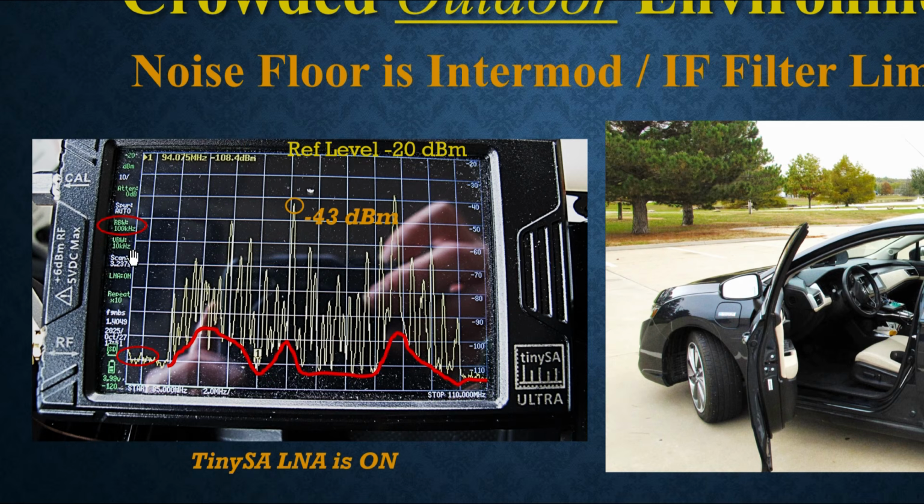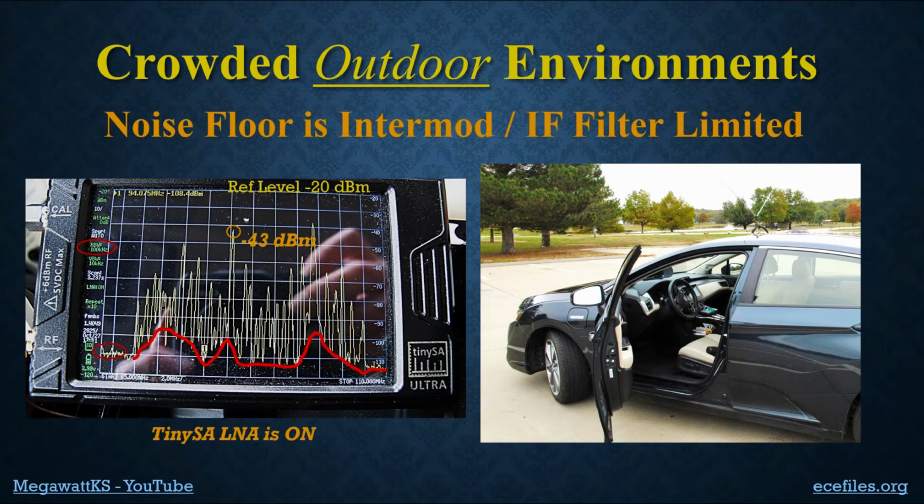So I had this spectrum analyzer set to a resolution bandwidth of 100 kilohertz. And in the FM broadcast band, the stations are spaced by as close as 200 kilohertz. So the filter can't roll off enough to be able to see stations adjacent or between if they're very, very weak. And I think that's what's going on here. All right, let's move on.